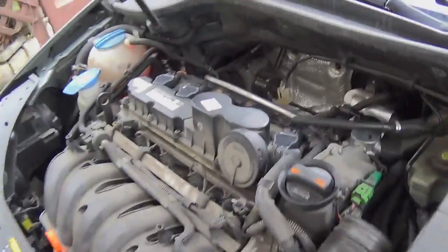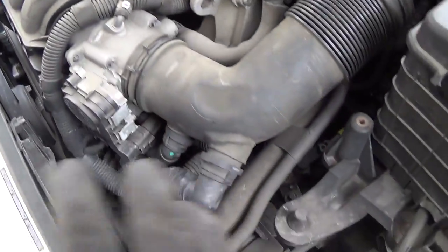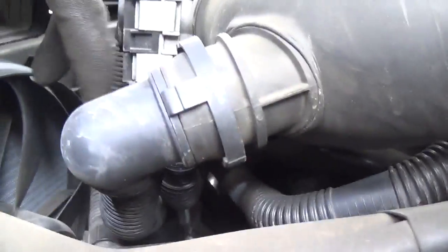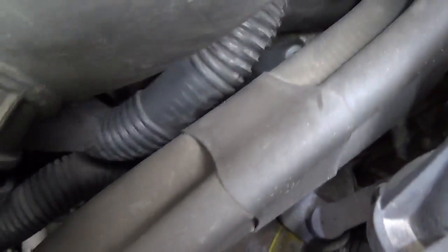Alright guys, I got the top air box off here, just taking a visual inspection of this secondary air injection system since I've never worked on one of these before. The air pump itself lives under the intake manifold, and you can see here's the intake air pipe coming from the air cleaner side, and then there's a plastic pipe right here, the one I'm pushing on, that sends air to this air diverter valve.